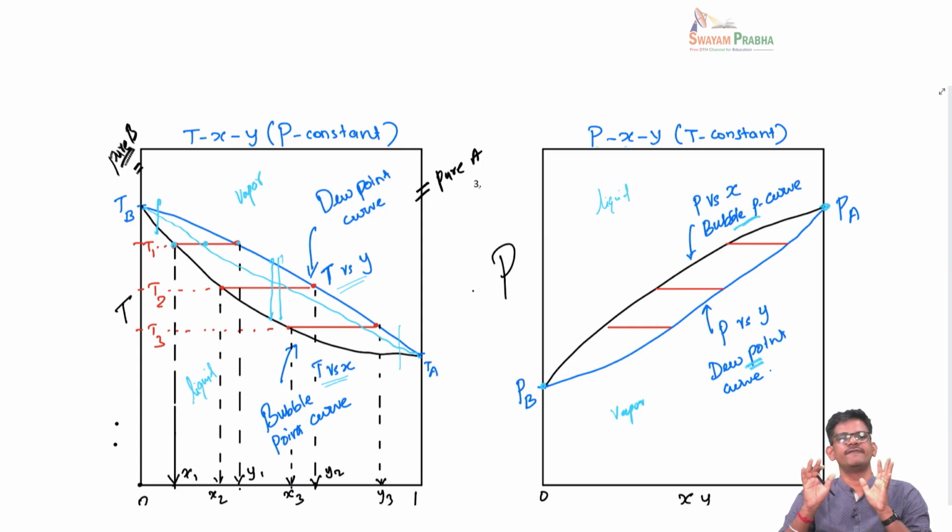You have to make yourself very flexible and familiar with this kind of information, how to process a Txy diagram, how to process a Pxy diagram. They carry the same kind of information, but we are using different variables to characterize the phase diagram. Okay, are there any questions about these diagrams? Do you follow what I am trying to say here?